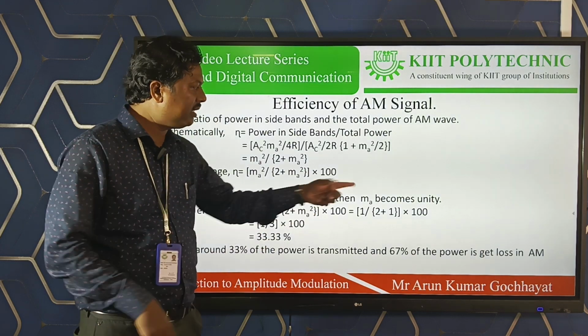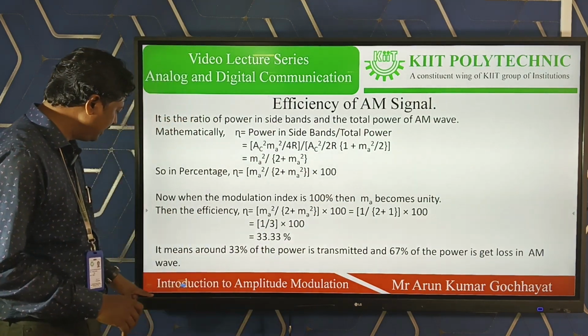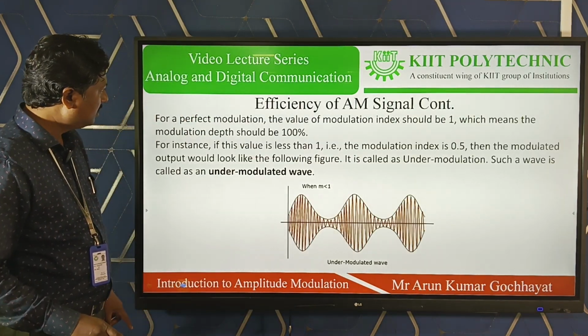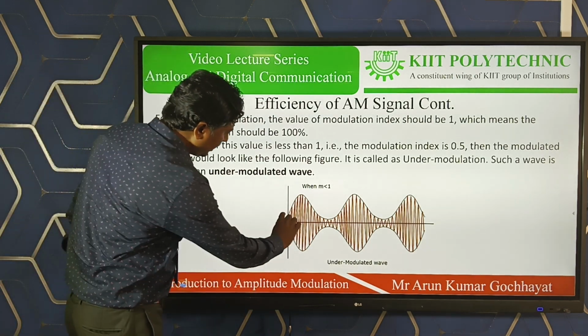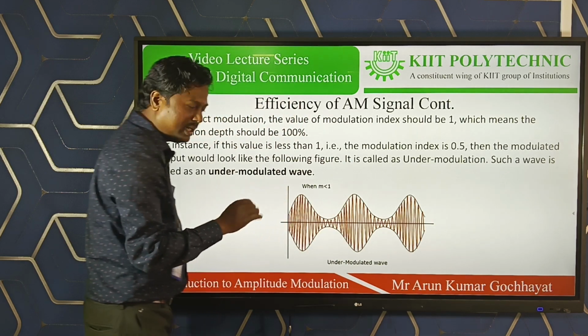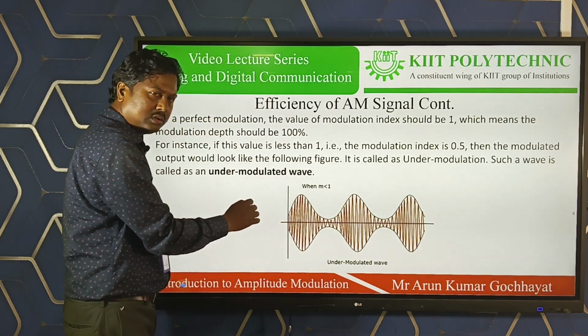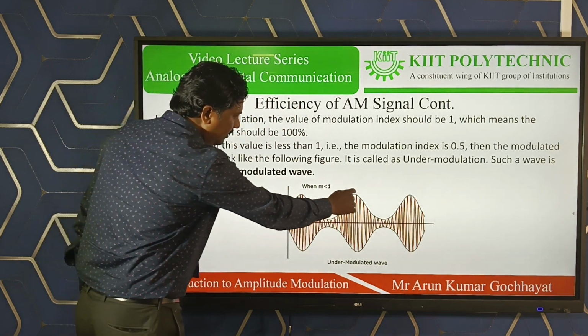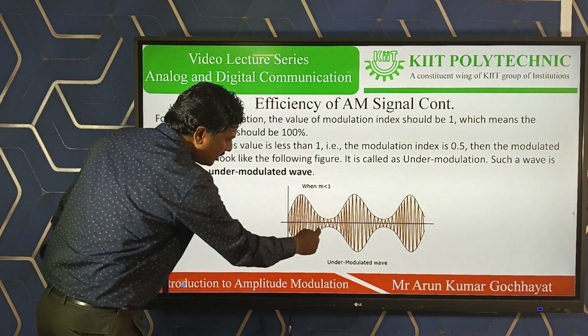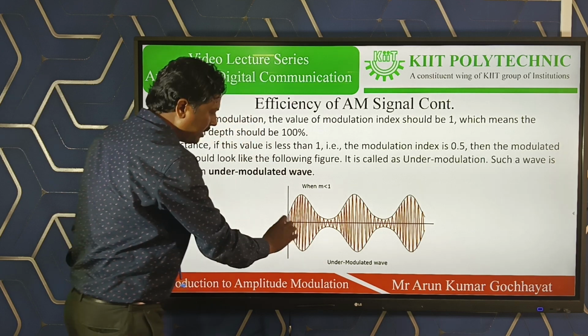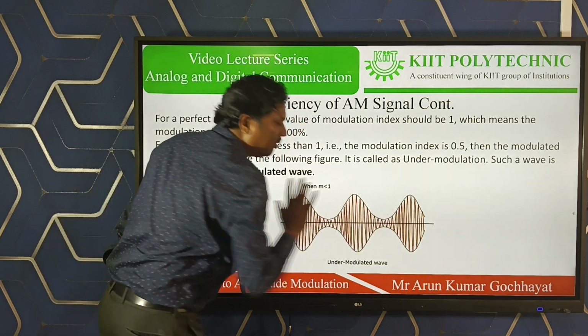That can be understood while visualizing the video, that I will say. So here what happened, see, this is the upper sideband, this is the lower sideband, and the middle one is the carrier portion. Now if you look over here closely, you are having the sinusoidal value, that means the message is present in the upper sideband. Even the sinusoidal message is present in the lower sideband.